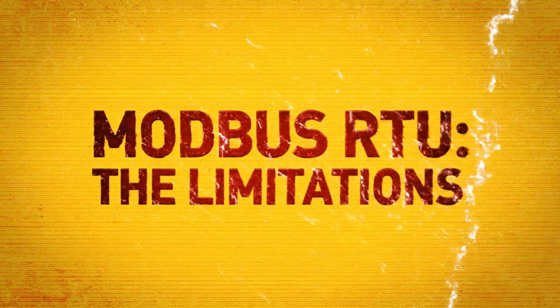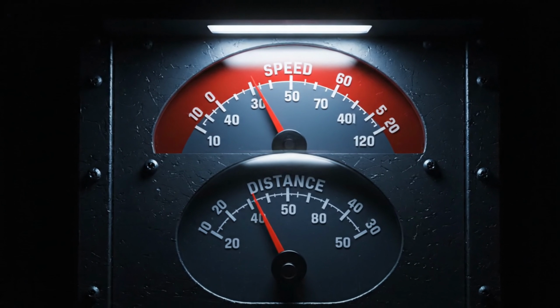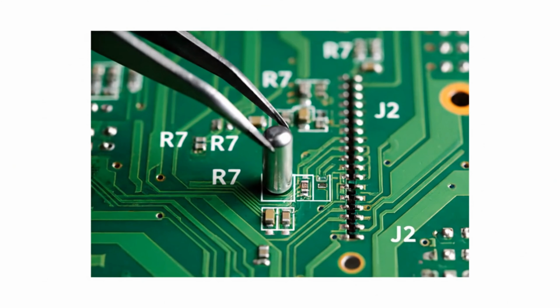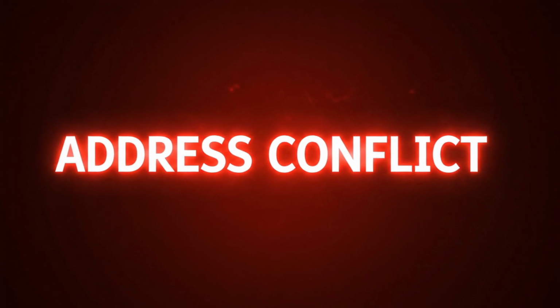But RTU does still have its limits. You're capped on distance, you're capped on speed, and you're working in a daisy-chain network where every device shares the same line. If you've ever added one device and suddenly had to rethink your addressing or your terminations, you know exactly what I mean.